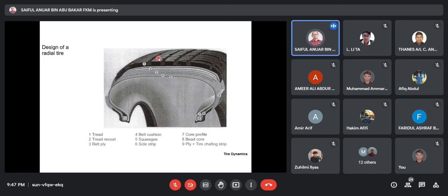The tire pattern can control NVH, and water dispersion, meaning it is going to swipe the water from underneath the tires towards the sides. That's why, if you see over here, this is a groove to swipe the water away towards the outside direction of the tire. That's the purpose of this, other than minimizing rolling resistance while at the same time providing tire grip.